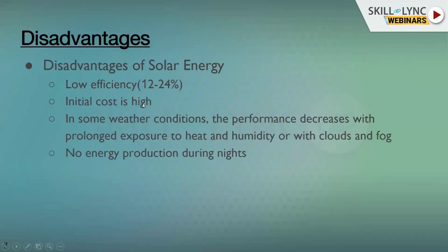As for the disadvantages of solar energy, mainly the initial investment for a solar energy system is very high compared to fossil fuels, as well as hydel power stations. Photovoltaic modules and inverters contribute more than 60% of the investment for the project. And it also has low efficiency.